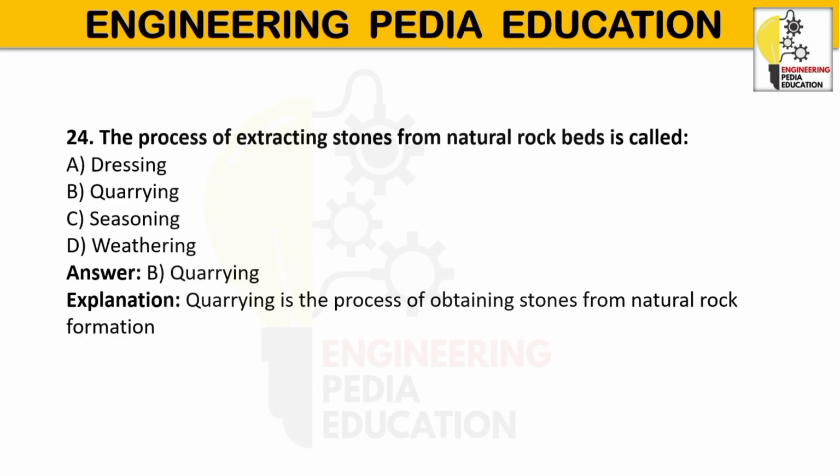Methods of quarrying are digging, firstly for soft stone; heating, rarely used; wedging, using wedges to split rock; and blasting, using explosives for hard rock. Steps in quarrying involve removal of overburden, that is topsoil, marking the stone block, cutting and separating the stone, lifting and transportation.